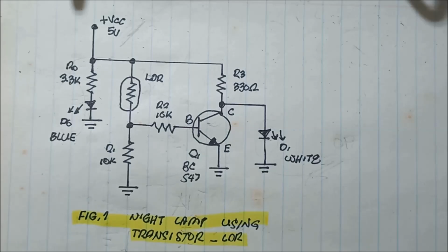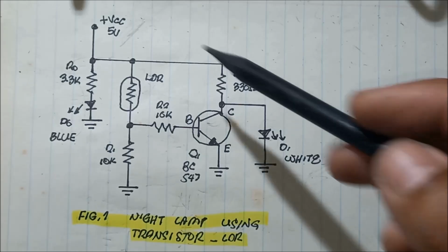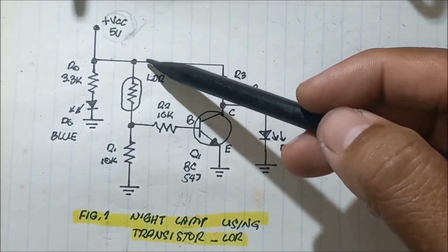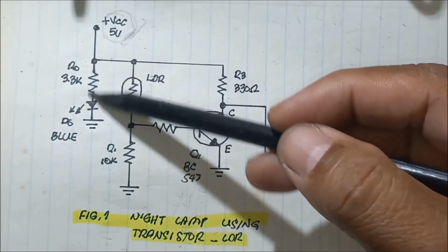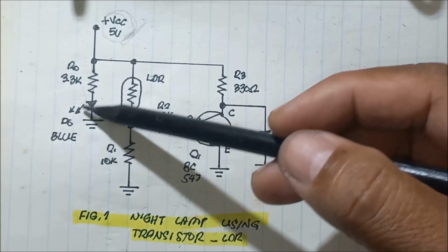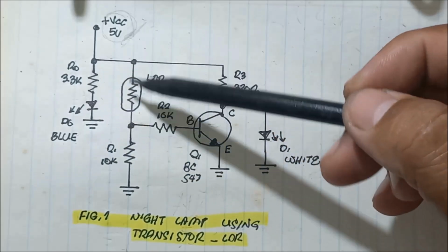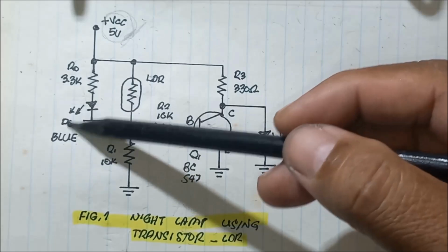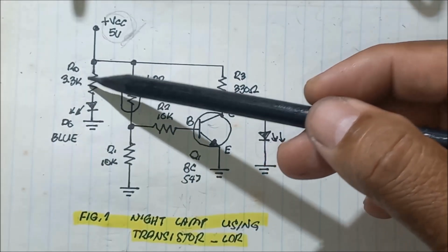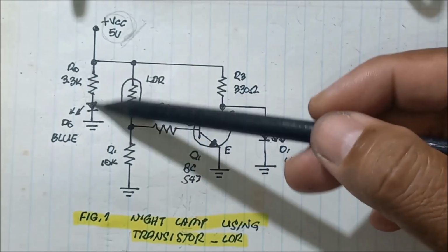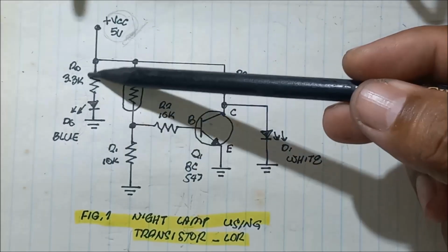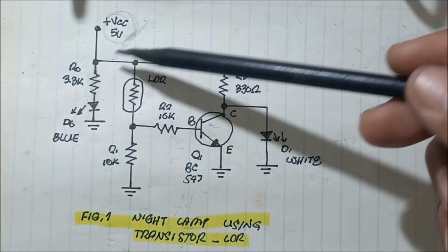So for the initial state of the circuit, when we power on the circuit using the power bank, current flows into the power LED. It turns on this power indicator. It means we now have the circuit on, using this blue LED and a 3.3K resistor to protect the blue LED from damage. It is a series, current limiting resistor.